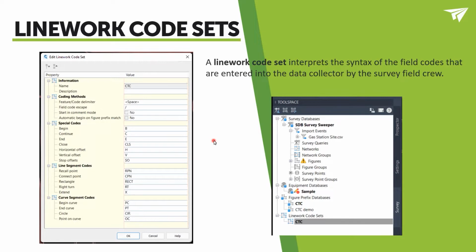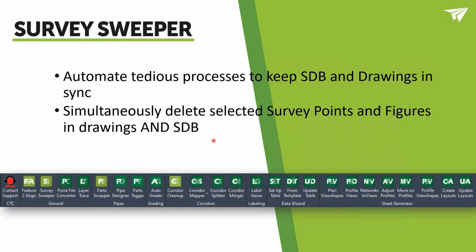Now, once we jump over to our survey sweeper, I'm going to show you how our survey sweeper actually automates this process and allows us to take the mistakes out, as well as points. Once we start our survey database and we're entering points, our points are going to live in our survey database. And once we make corrections to codes that may be miscoded, maybe there's a letter missing, etc., they're still going to live in the survey database, and it speeds up the process of deleting these lines, deleting these COGO points, so we don't have to go back and forth. It makes it a lot easier and more streamlined to automate this process.